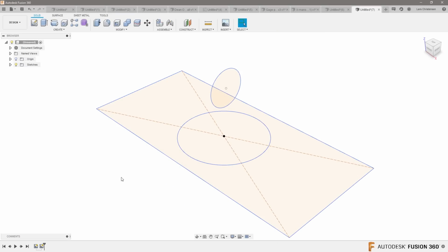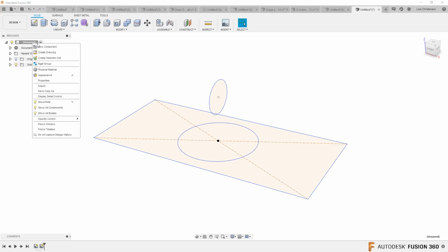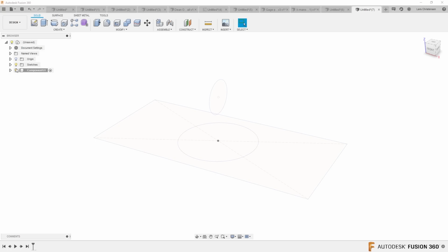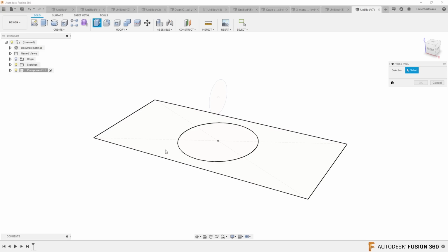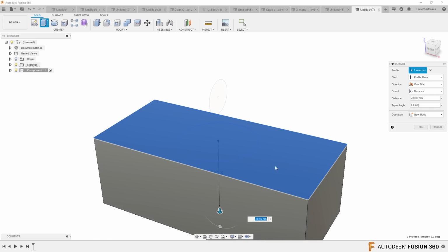Now what the top down means is that when we have drawn some of these helping sketches, maybe now we start creating extrusions from these. So I go in and maybe you even start new components. So there's going to be one component, right click that, and that component is now going to be extruded from that sketch I originally created.